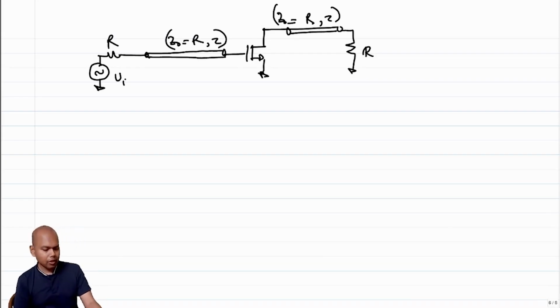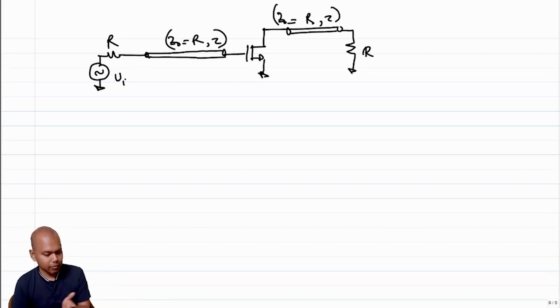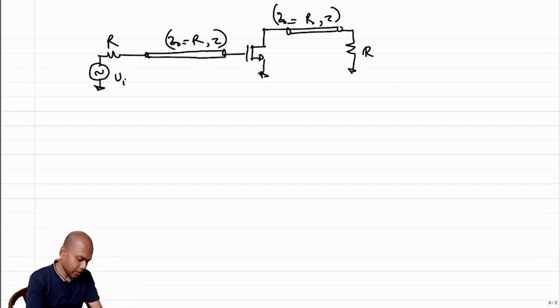These taus need not be the same, but without loss of generality, for the time being, we can assume that. Now, we understand that this common source amplifier, in a very simplistic format, has an input capacitance. So essentially this is a capacitor C, and I would like to understand what the value of this capacitance is, and I choose to do a Z parameter analysis.